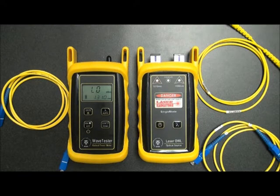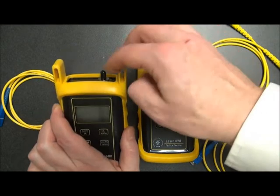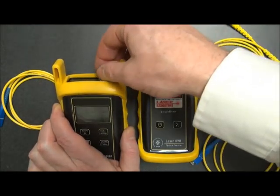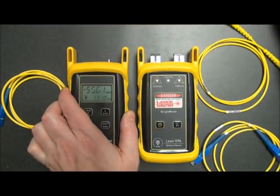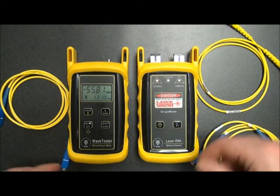You can also see that the display says low. Now the word low simply means that there's no measurable amount of light coming into the photodetector. As you can see, we have the dust cap on the detector port. So when we take this off, you'll see that we actually get a reading. In this case, we're reading room light, but we will actually get a real power reading when we connect in our patch cables when we're testing them. So I'm going to do that now.